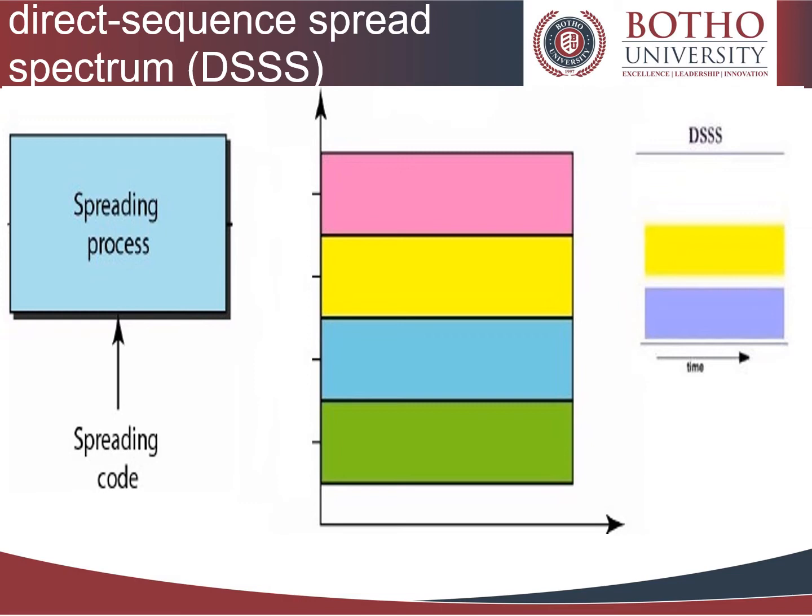The next form is DSSS, which is also called direct sequence spread spectrum. In telecommunications, direct sequence spread spectrum is a spread spectrum modulation technique primarily used to reduce overall signal interference. DSSS modulation makes the transmitted signal wider in bandwidth than the information bandwidth. The DSSS transmission employs a chipping code to spread the transmission over a wider frequency band than it would normally occupy. The direct sequence spread spectrum technique expands the bandwidth of the original signal.